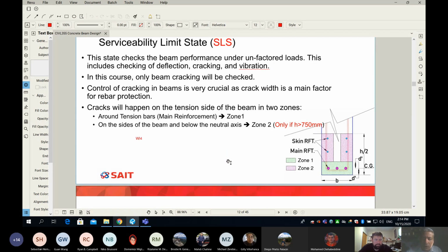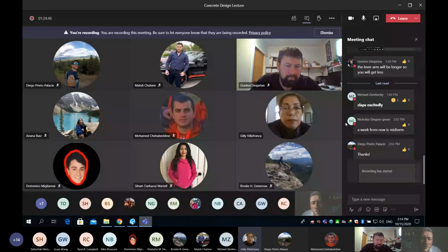5 over 384, and then WL to the power 4 divided by EI. Do you guys remember this term? Did anybody still remember 5 over 384 WL to the power 4 divided by EI? What is this for?